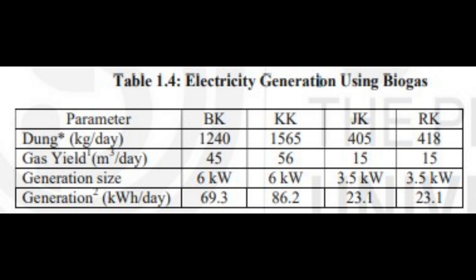3. The electricity required to be generated by the biogas-based generation system is evaluated for each month by subtracting PV generated electricity from the monthly demand. The remaining biogas is passed on for cooking purposes, if required. 4. Battery size is evaluated as discussed in step 4 of case 2. If the lighting load is able to be met by biogas generation, battery size is assumed to be 0. 5. The total life cycle cost of the system is evaluated.